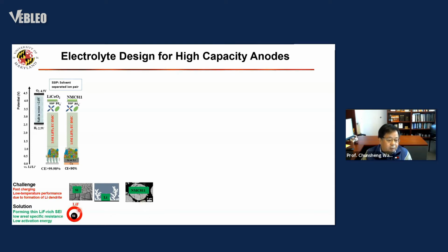We want the SEI to have less bonding with the substrate, like silicon, lithium, NMC811. Then when silicon changes volume, the SEI, not bonded, stays stable and not broken. Only the silicon inside shrinks and expands. So the electrolyte outside cannot penetrate. If it cannot penetrate into the crack, then there is a chance to self-heal, because lithium silicon, when the lithiation content is high, is plastic. It can flow and heal the crack. The lithium is the same thing.